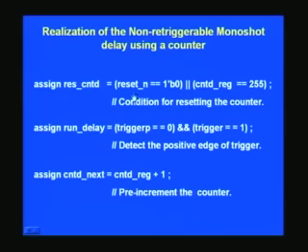So why not combine both in a single statement, and this is the OR statement that is doing it here. This is a logical realization, and each of them will return a 1 if the condition is satisfied. For example, if counter 2 is 255, then it returns a 1, and this will influence this reset signal as such.